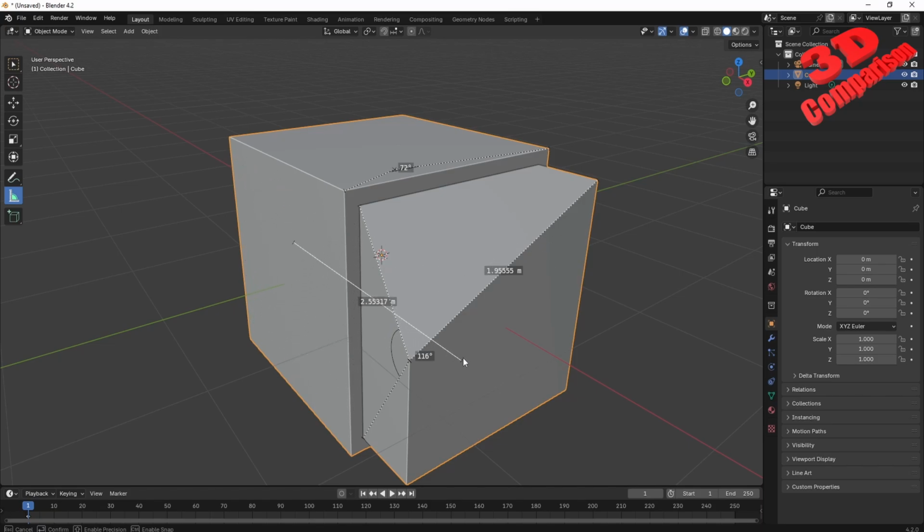And if I will move it over here, we're gonna see that over here, we have 2.5 meters. And if I will move it over here, this inner inset will only have a width of 1.7 meters. So this is how you can easily do some measurements. This is very convenient, especially if you are working with 3D scans, since we're gonna see Blender has a very good workflow when working on reverse engineering.